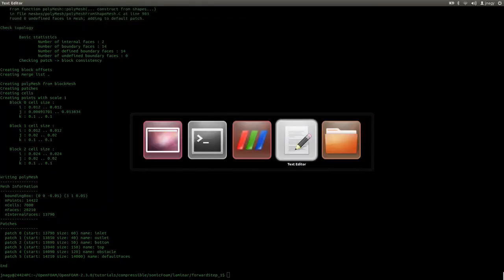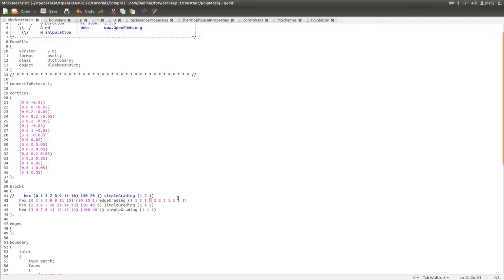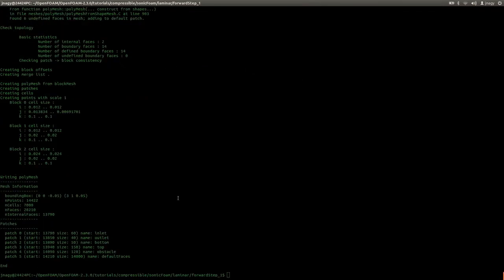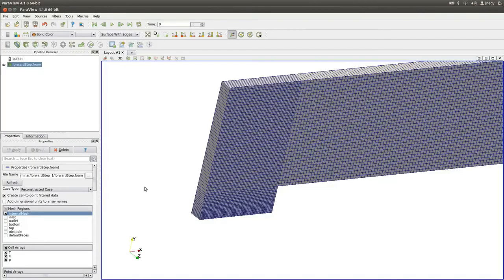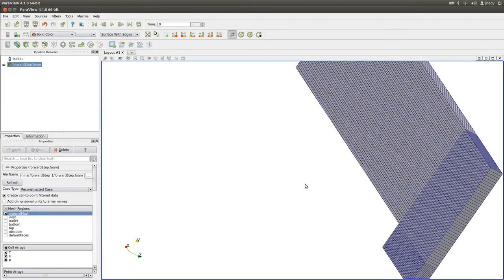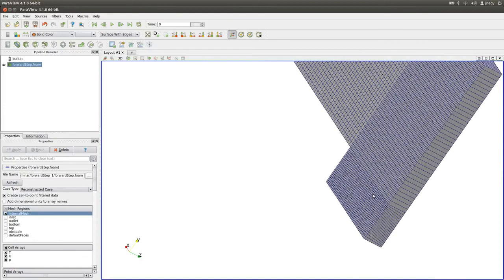And if I now go back to block mesh and for example change here one value to 0.5, so on one edge the refinement will be the exact opposite. Refresh, and here is the same, but as you see on this edge the refinement is inverted. And this does not make sense for a 2-dimensional mesh, but for a 3-dimensional mesh it might make sense.